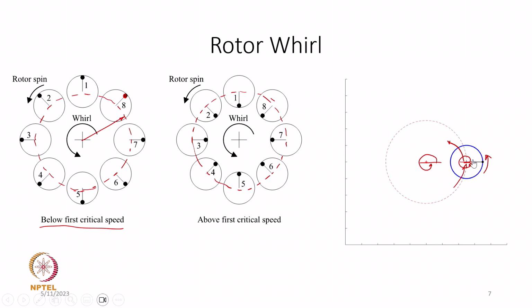That is what is typically called in practice of rotor vibration a synchronous whirl. Synchronous whirl means it is synchronous to the speed of rotation or spin motion. But again, let me remind you that it is this whirl amplitude that is vibration, and the spin motion is the rigid body rotation of the shaft about its own axis. All right. So, this is how it looks.